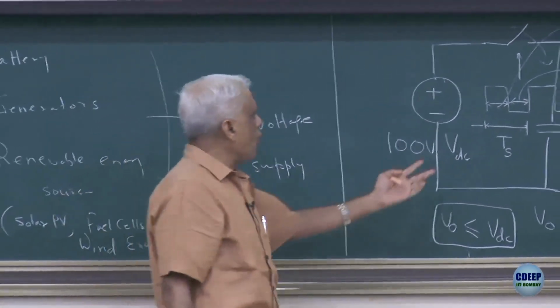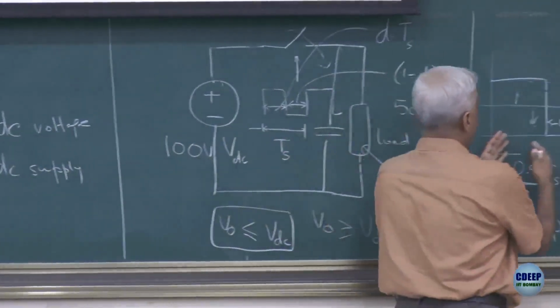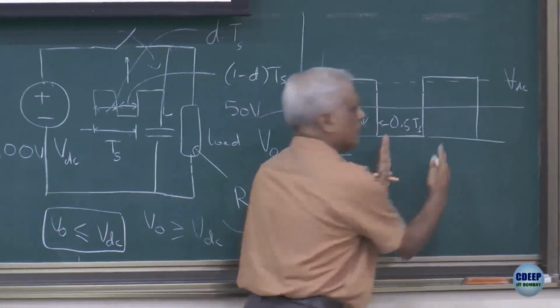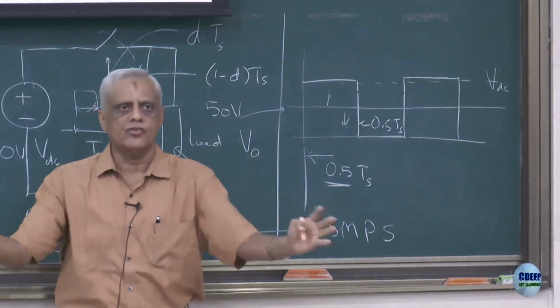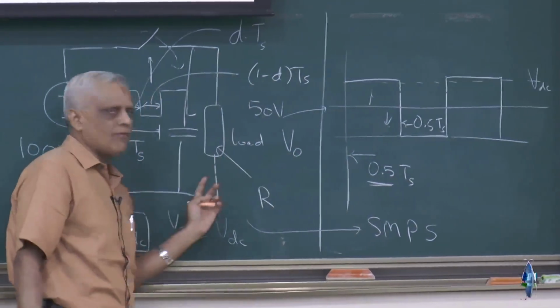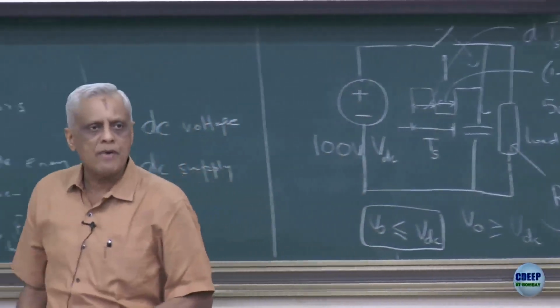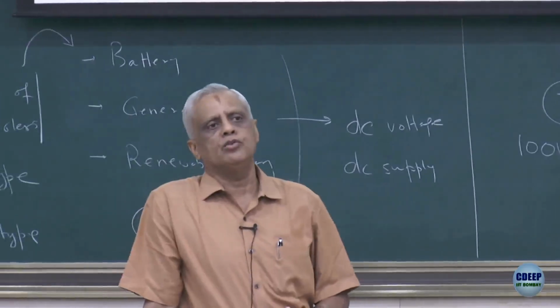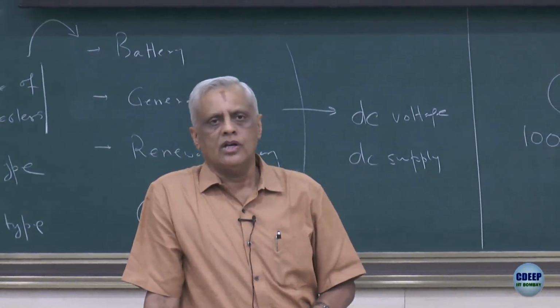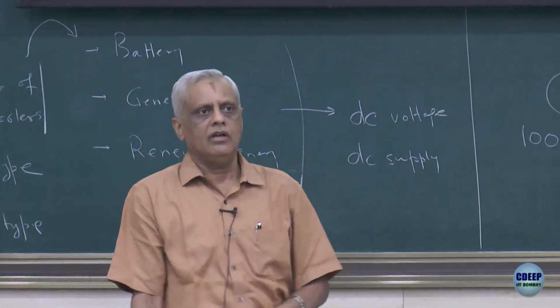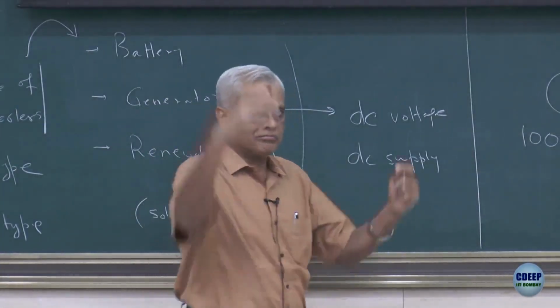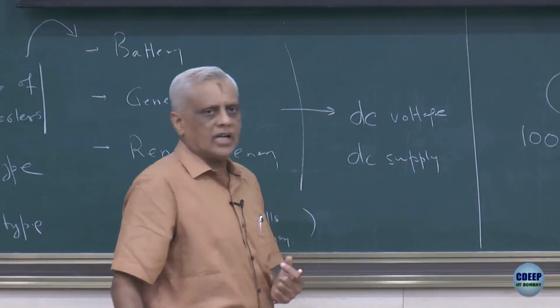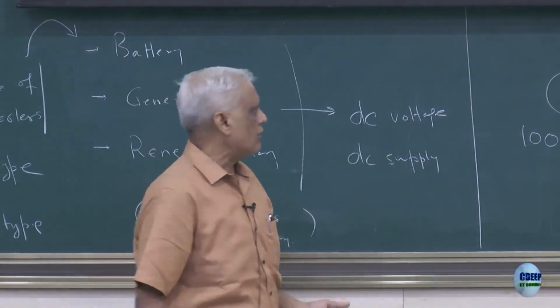And the higher the frequency, the smaller the gap will be, as you can see. It will shrink, and a smaller capacitor filter will be able to give you a nice constant DC output voltage, without any valleys or deep pits, a nice smooth waveform.